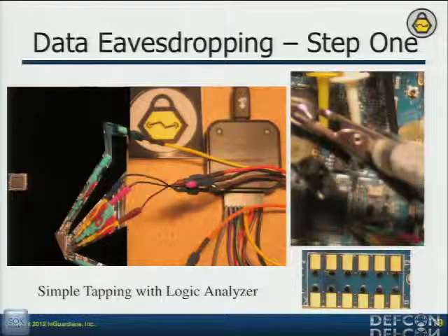On the right-hand side, if I can't get the micro grippers on there, if it's something like BGA components, or they're really small and I can't get the grippers to grip on, then I'll tap with hypodermic needles. It's really good because it's got that point and it'll grip on there. But the problem with both of these things is that if I tap this with my elbow or my knee when I'm standing up to go do something, all of that stuff pops off. You don't know how aggravating it is, trying to get those hypodermic needles on there for 30 minutes just to look up, bump it, and have to do it all again.